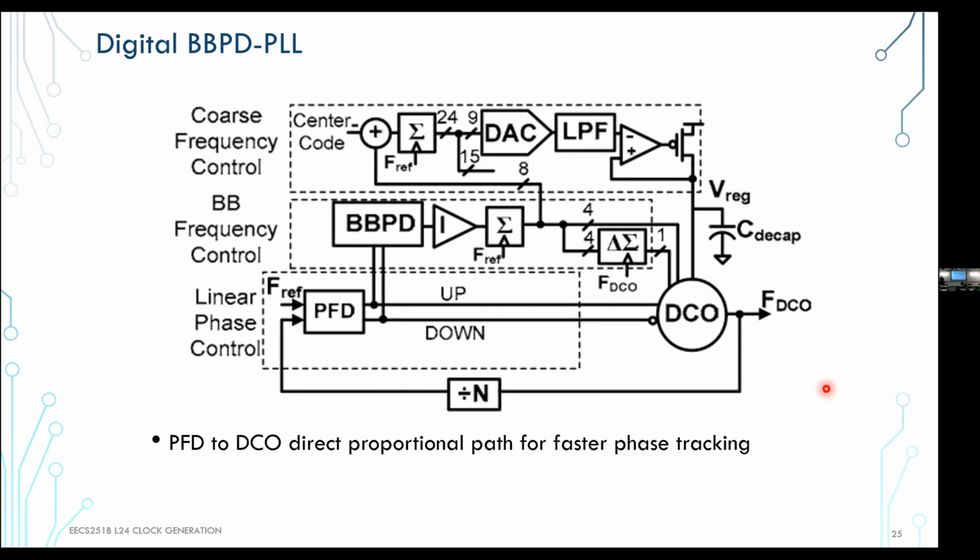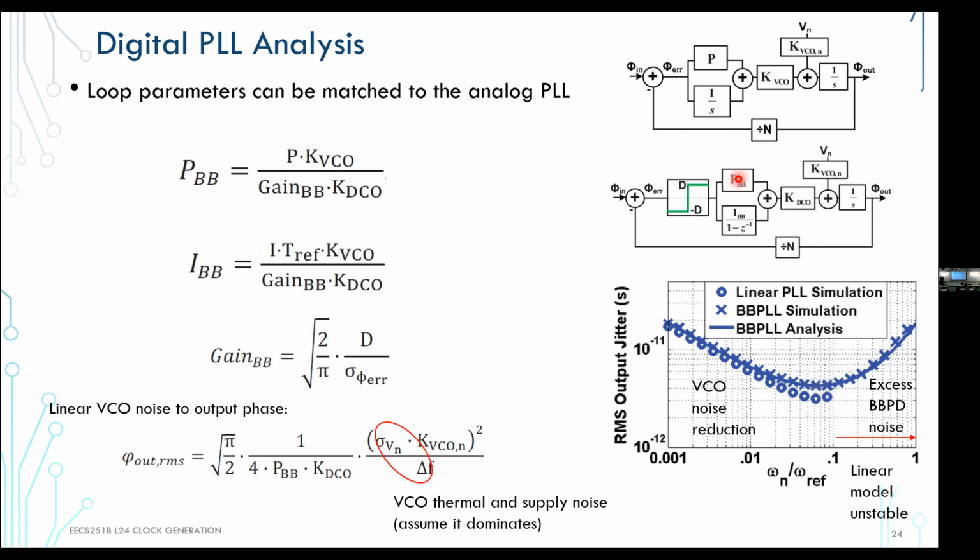To actually build this, there are a few more bells and whistles you need to add. It's not as simple as this, because you want this PLL to be agile. If you go back here, it's not easy to set up these parameters so that the output of this detector can react quickly through the proportional path.